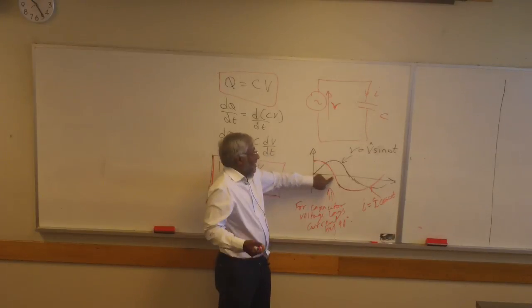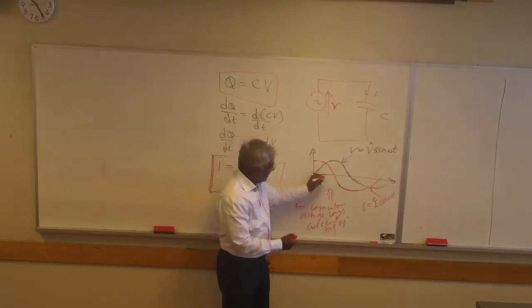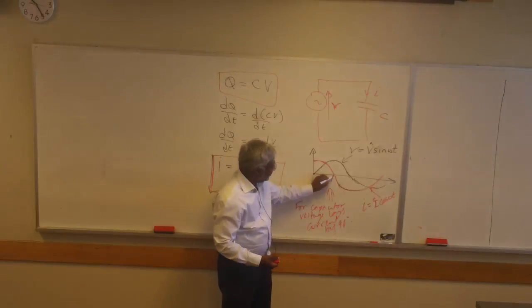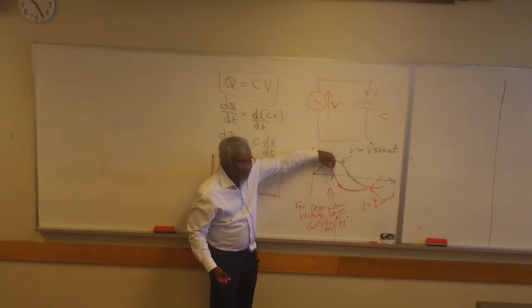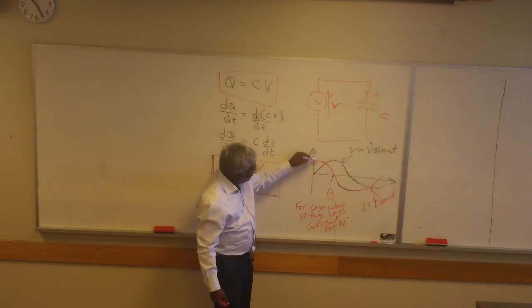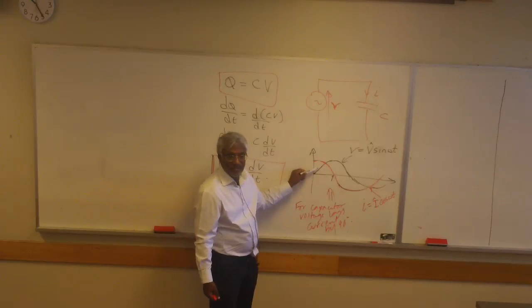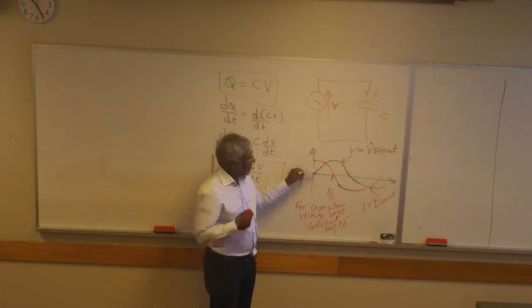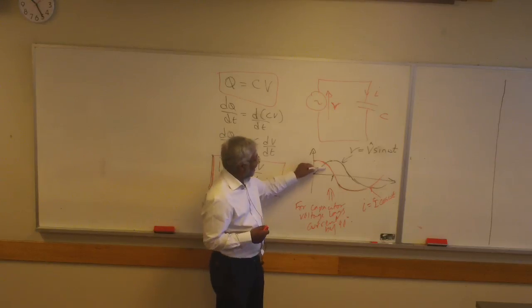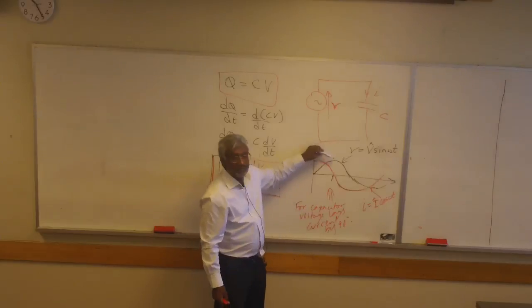And in practice, that makes sense. I am over here. Am I charging at this point here? Am I charging or discharging the capacitor at this point? Before this point, from 0 to 90, am I charging the capacitor? It's charging. I know I am charging it because the current is positive. So the current is going into it. So I'm charging it. Therefore, its voltage goes up.